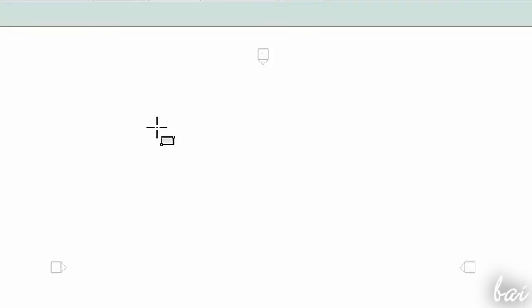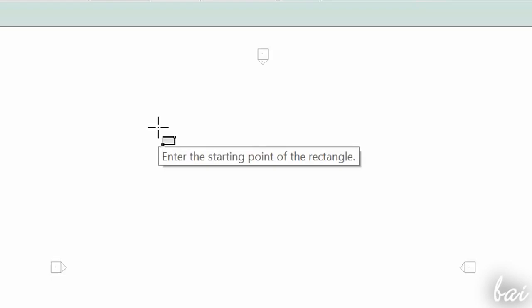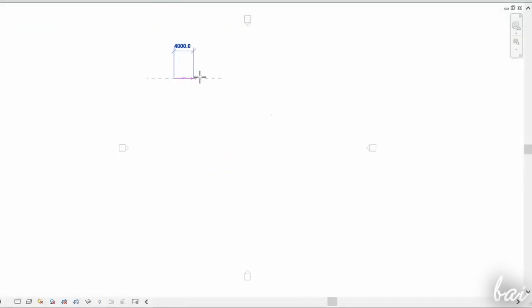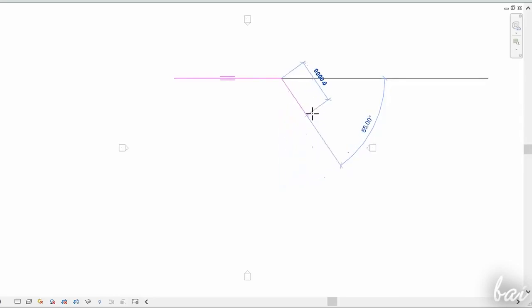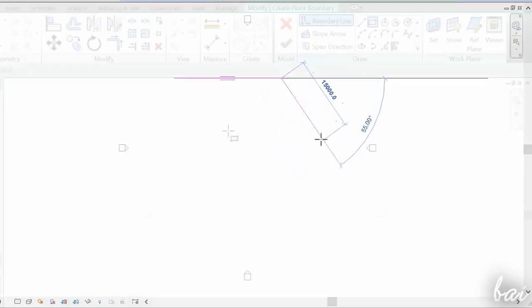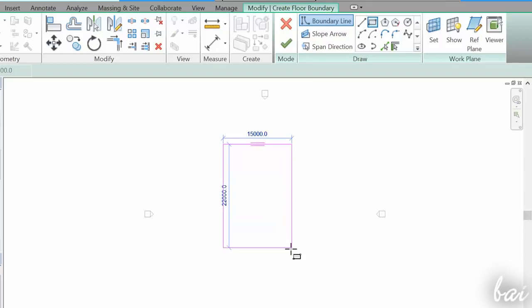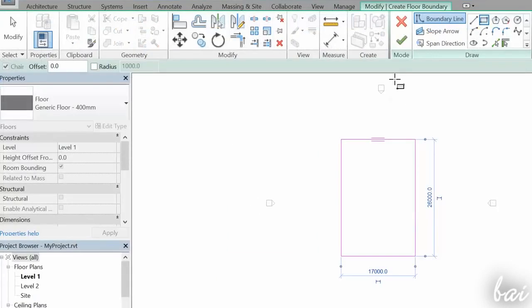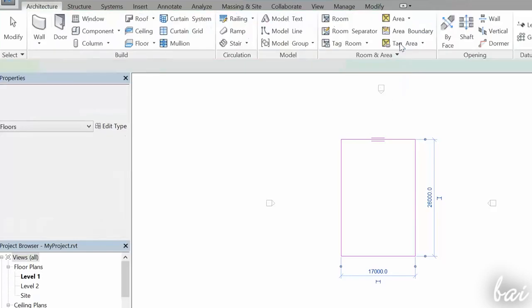Revit helps you while you draw. If you fix your pointer for some time, a dialog box shows what to do. Plus, you'll always have information about side length and angle measurement on the object in progress. As long as a drawing tool is enabled, Revit is in edit mode, which is used to create and edit sketches of objects, shown in pink color.